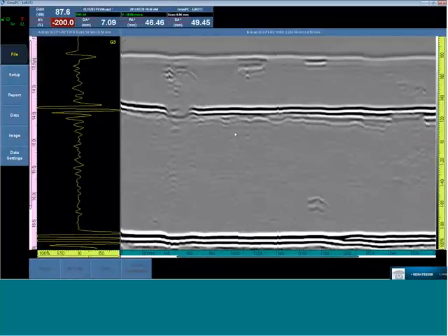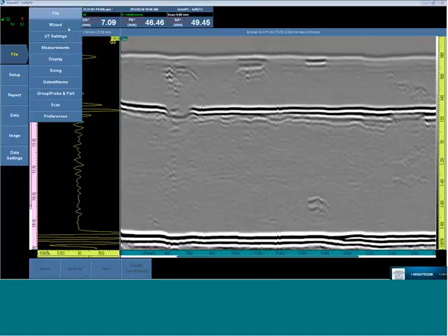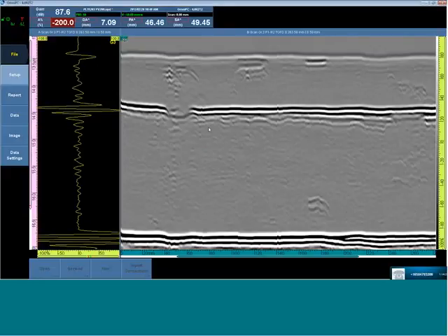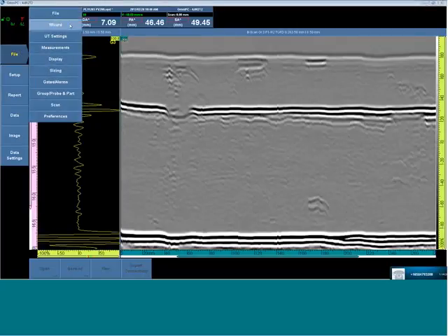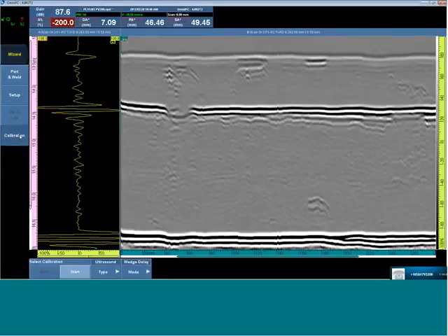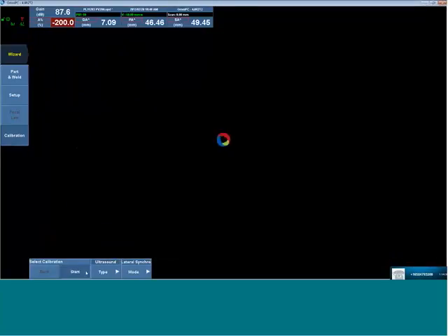The offline viewer or analysis software we're going to be using is OmniPC. OmniPC allows the same user interface as the OmniScan MX2 offline on a computer. So we have the raw data that we see here in our TOFD group. We go straight to the wizard, select calibration, lateral wave synchro, start.